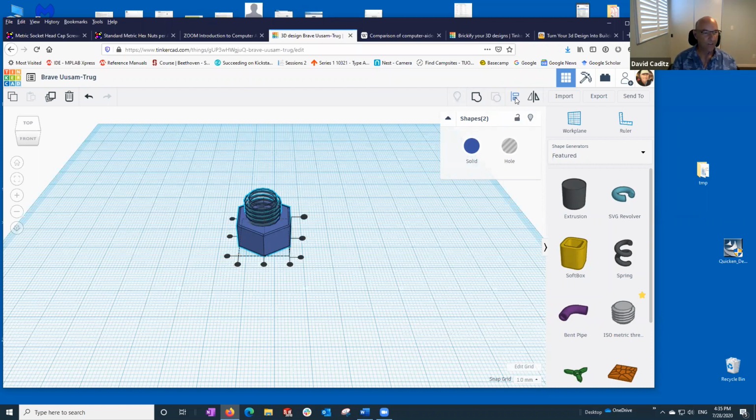It takes a second to understand how this all works, but notice these dots here. There's 3 dots on the bottom and 3 dots on the sides. Each side has 3 dots. So if I select the middle dot, it's going to align it to the middle here. And if I select the middle dot here, it'll align it to the middle in the other direction, in the Y direction. I could also have selected align it to the edge, and it'll move it down to the edge. But that's not what I want. I want to align both the X direction and the Y direction in the middle. So alignment is a really important feature.